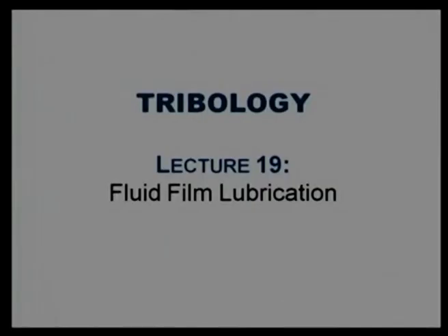Welcome to 19th lecture of video course on Tribology. Today's lecture topic is fluid film lubrication. It involves mathematical analysis. It involves a merger, or we say marriage, of three equations. Equation number 1 is conservation of momentum, conservation of mass, and conservation of energy. We need to marry these three equations to get overall fluid film lubrication equation.